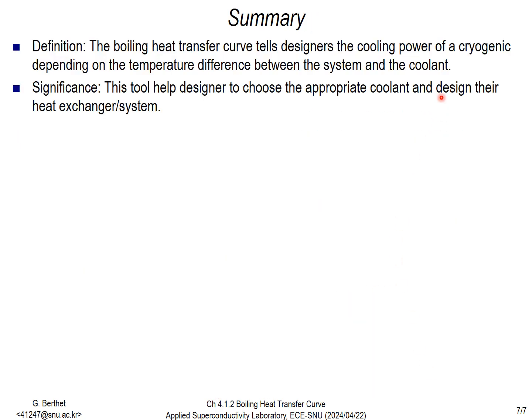To conclude, the boiling heat transfer curve tells designers the cooling power of a cryogenic, depending on the temperature difference between the system and the coolant. This tool helps designers to choose the appropriate coolant and design for their heat exchanger or system.